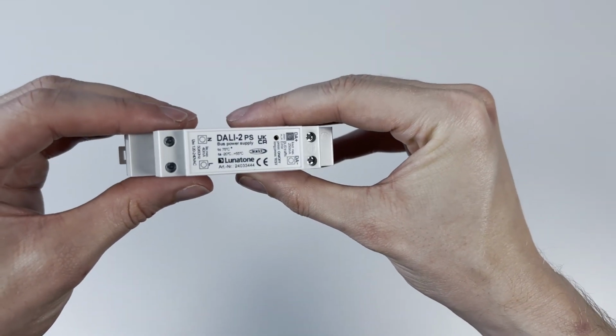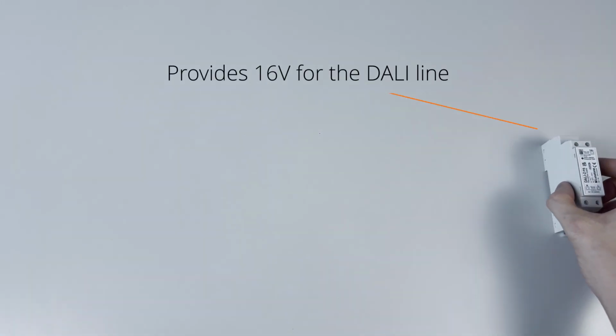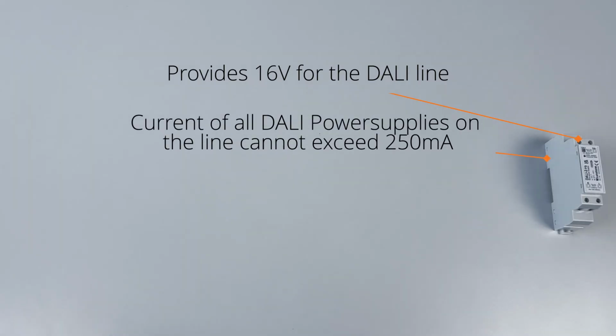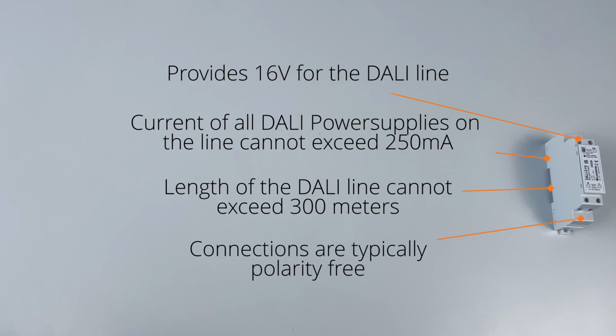Let's meet the devices. 1. The DALI power supply. The DALI bus requires a 16-volt power supply. The combined current of all power supplies on the DALI line cannot be more than 250 milliamps. The length of the DALI line cannot exceed more than 300 meters, and the connections are typically polarity-free.